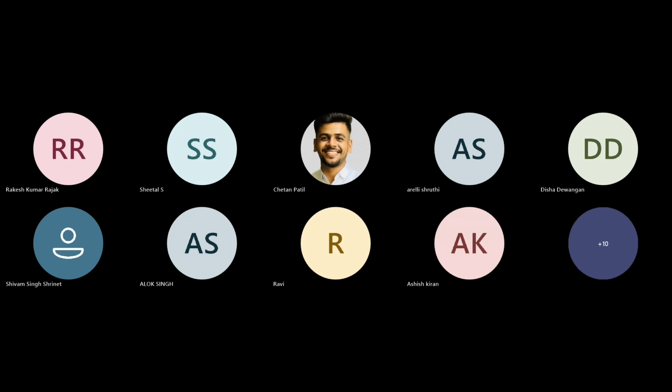Okay, I'll just let you know how to overcome the particular errors in over constraint kind of models. But let me just complete this auto time stepping over here. So basically, whenever you want to make divisions of whatever load you have applied, you have two different methods. Either you can go with auto time stepping.